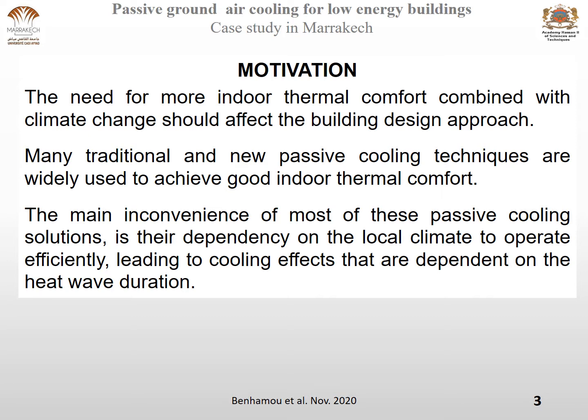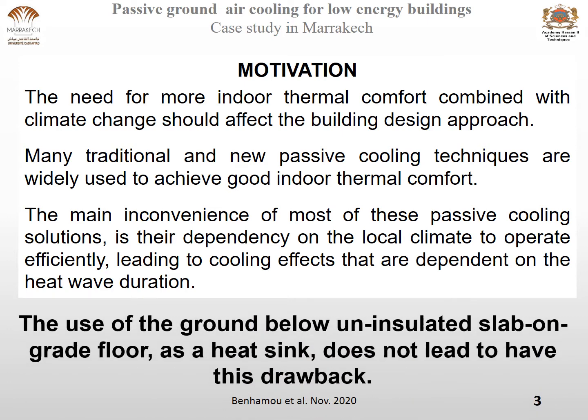However, the main inconvenience of most of these passive cooling solutions is their dependency on the local climate to operate efficiently, leading to cooling effects that are dependent on the heat wave duration. However, the use of the ground below a non-insulated slab-on-grade floor as a heat sink does not have this drawback.